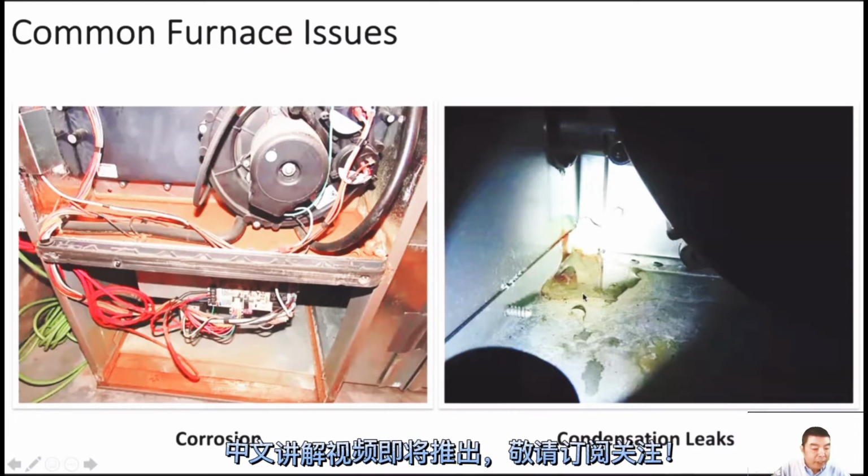So this one is a leak from the furnace. But sometimes, for a category 1, if you see rust and there's no air conditioner, maybe there's a humidifier. The humidifier causes the same trouble as the A coil.